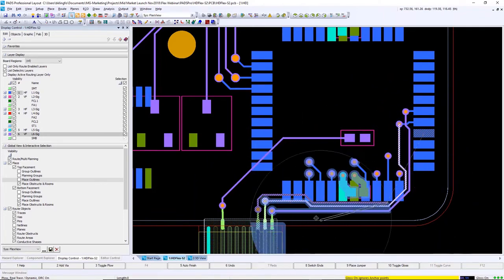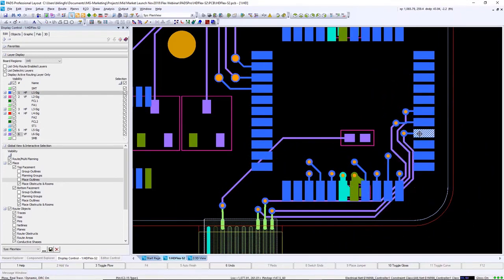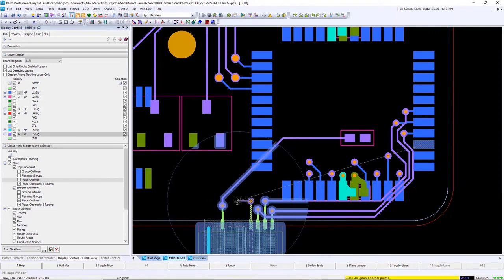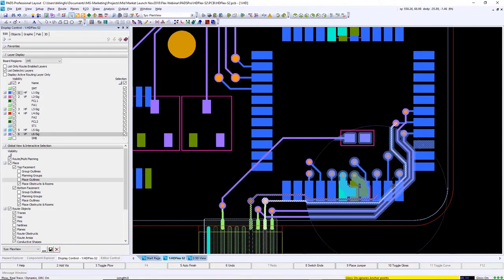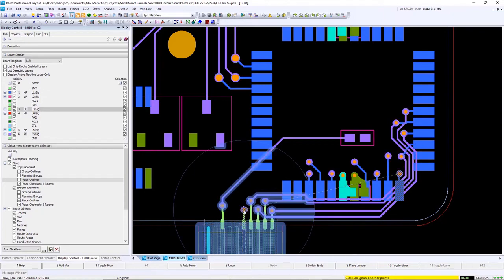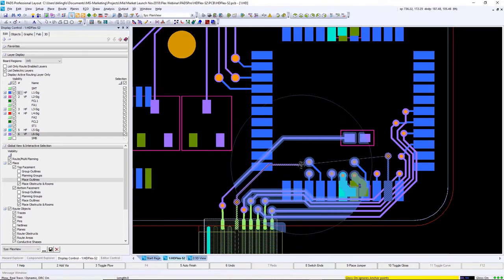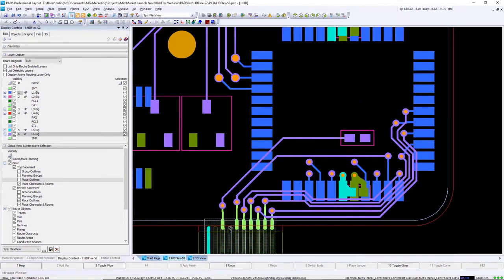The other advantage is traces routed in the rigid area are now using a smaller clearance rule so they don't consume too much space. This shows the power of using design rules to your advantage instead of doing everything by hand. Also notice while routing how easy it is to guide a trace into a tight spot and let the tool do all the work by pushing and shoving others out of the way, given there's room to do so.